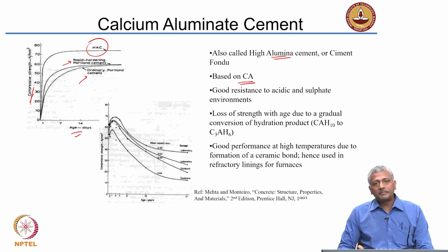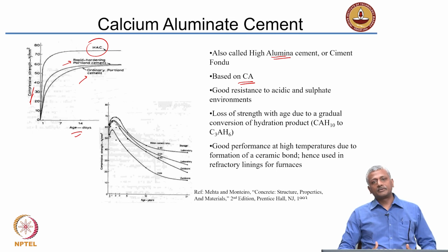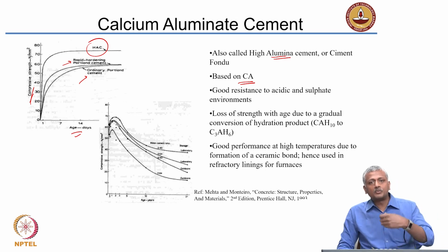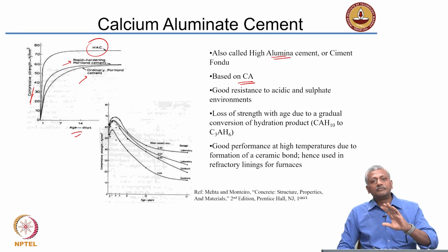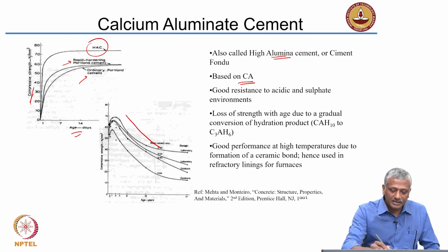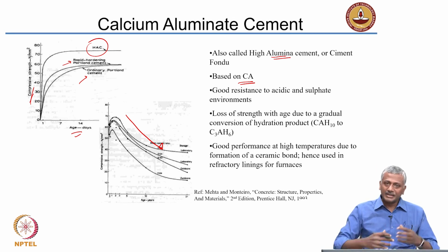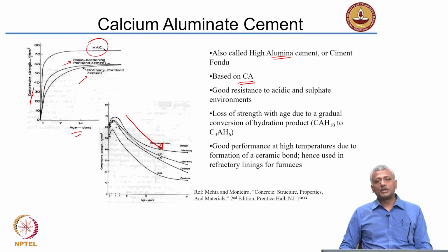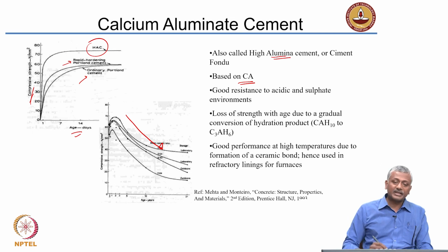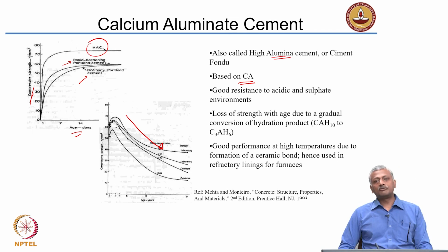Right. So, they started developing a lot of structures with high alumina cement, which gained strength rapidly. The problem was, as the concrete made with this cement was exposed to the external environment with moderately high temperatures and humidity, the strength basically dropped over time. Okay, this happens because of an internal chemical compound composition which changes as it is subjected to continuous exposure to temperature and humidity. And because of that, you have a problem of using the cement for normal construction.